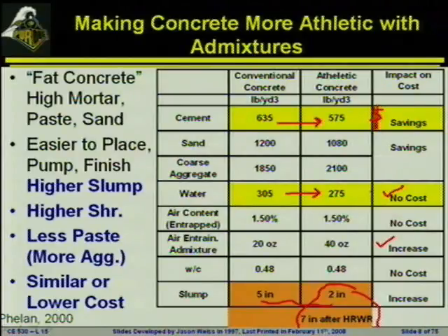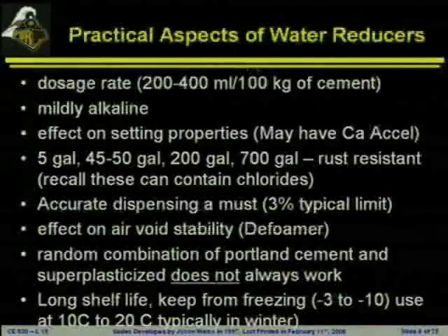And to say that they don't react the same way water reacts, but you can have an interaction between different things. So one of the things that you will notice is the air entrainer, for example, on this graph. You'll notice that we said that we had to increase the air entrainer a little bit. And sometimes this happens because the water reducer will change the surface tension of the fluid and make it harder to stabilize some of the bubbles. I'm not sure if that answers the question that you were asking.